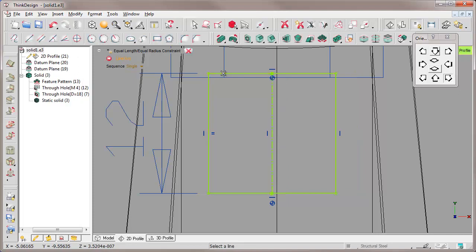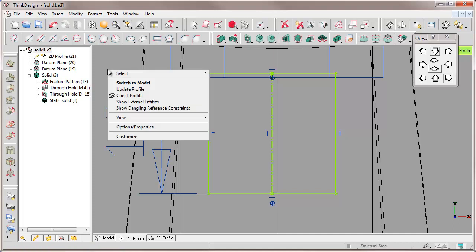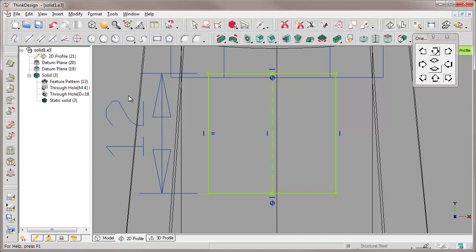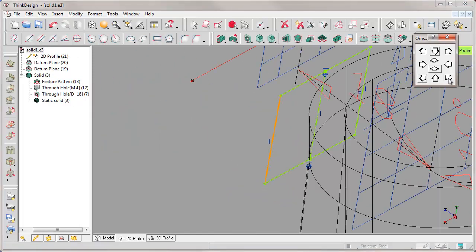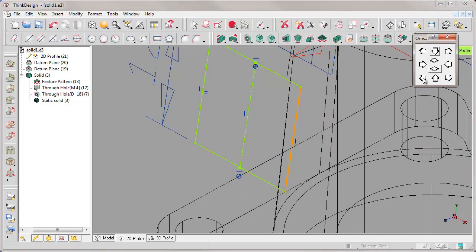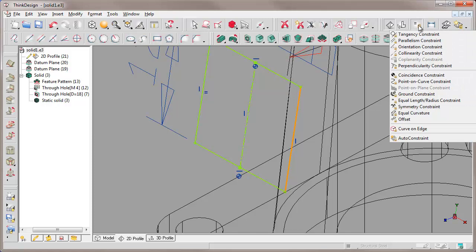Then, by a geometric constraint, we specify that these 2 lines must have the same length. As a consequence, also the others turn out to be constrained. In fact, checking the profile, there are 2 degrees of freedom, so from the geometric point of view, the square as an entity is constrained, but the position of the square in the x or y vector is not managed so far. We actually can drag it, since it's free to move on the xy plane.